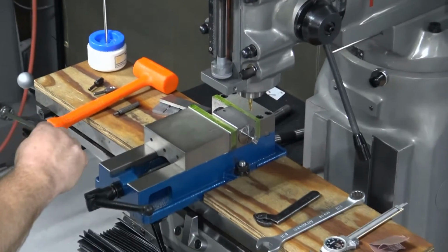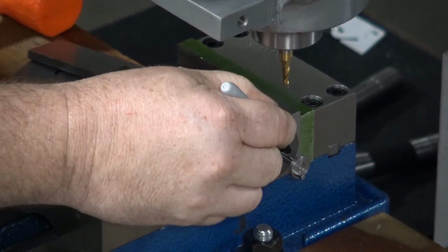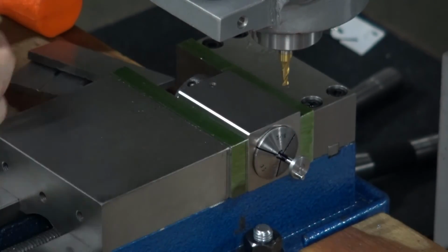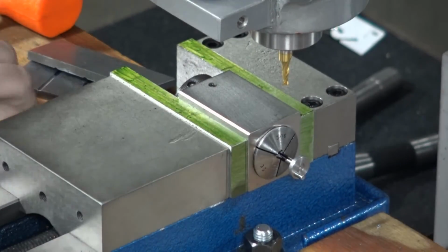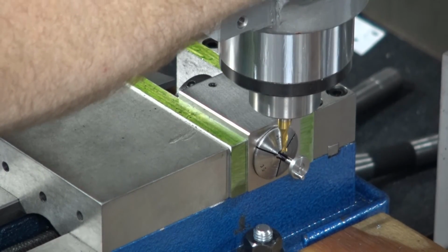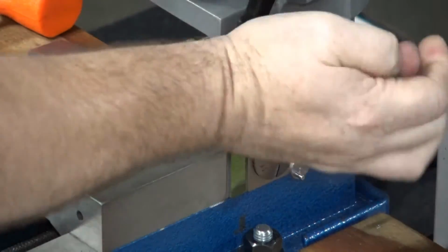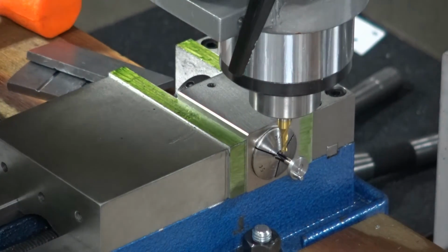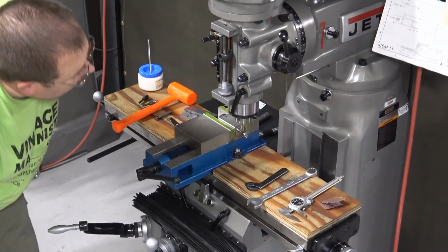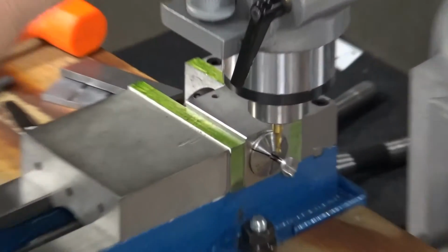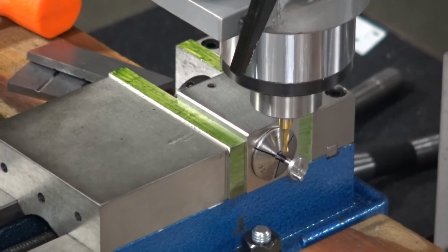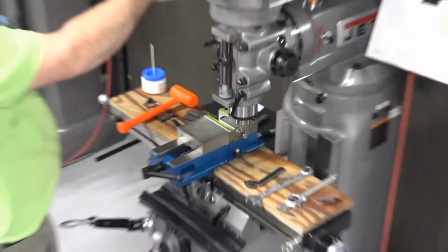But before I do my touch off, I'm going to color the top surface of that crankshaft. Okay? That's going to make doing my touch off a lot easier. Now I want to make sure that my end mill's stuck out far enough that it's not going to hit anything in the collet system. Okay? Now 775 RPM is nothing more than switching to low range on the power switch.